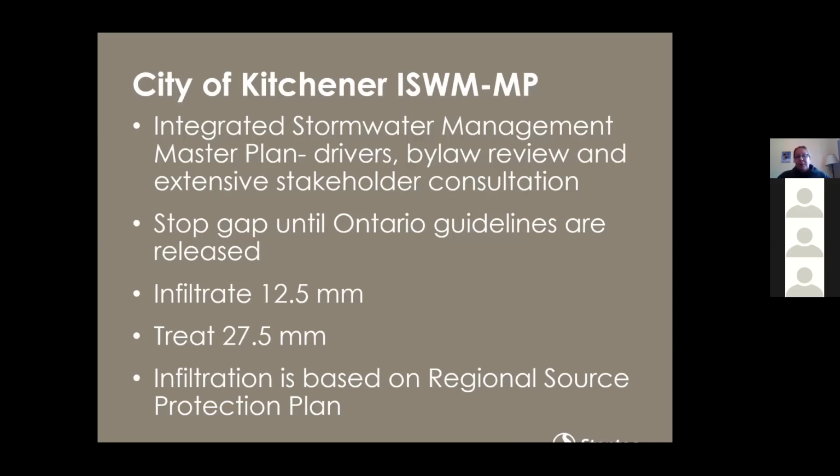Interestingly, our infiltration here is based off of regional source protection plans, and that's our groundwater source protection. So depending on where you are in the city, you may be able to infiltrate more or fewer types of surfaces. The current interpretation of the infiltration policy does look at each target separately on a per catchment basis for impervious area only. So you don't have to infiltrate off of lawns, provided that those lawns don't proceed to flow over parking lots or roadways.